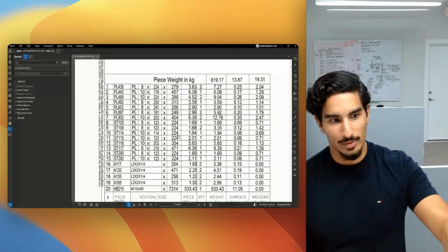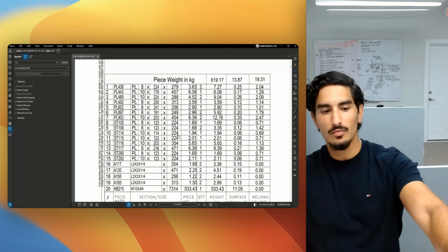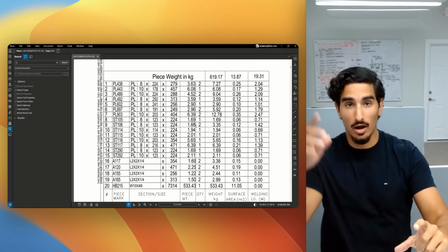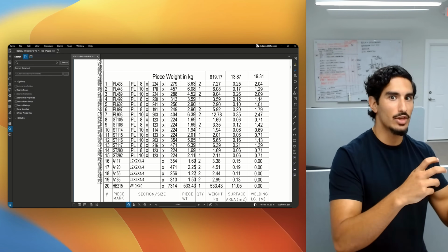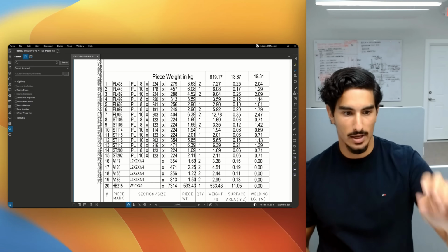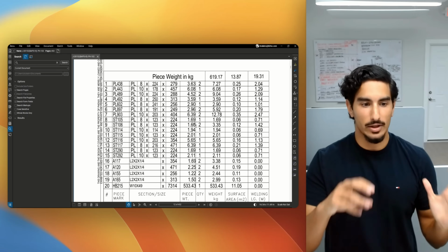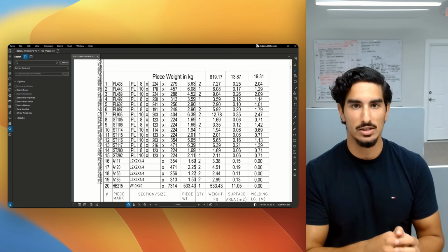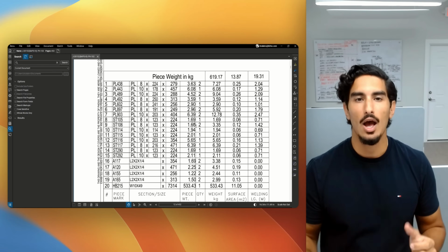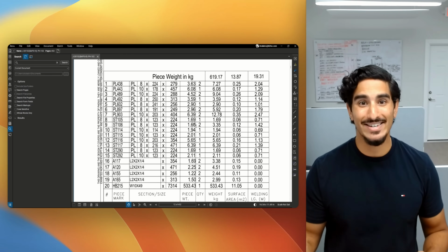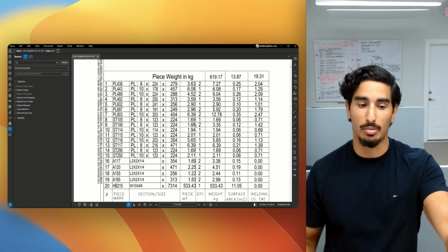And the bill of materials doesn't always reflect the shape of the T shape, but in the weight column, that's where the actual weight of the member is. So if it's a T shape, the weight will be associated to the T, not the rectangle that it's shown in the bill of materials. And what the AI system decided to use as a verification method was, let's go read the drawing of the piece mark, take out the geometric properties from the drawing that I am reading, multiply that volume by the density of steel, and then compare that overall weight that it got versus the bill of material.